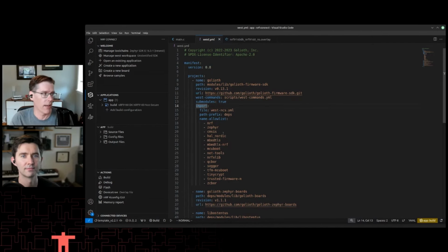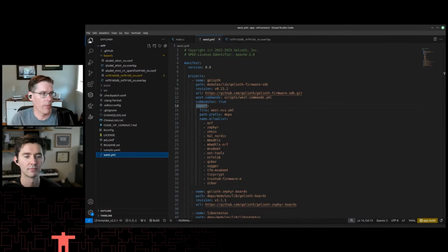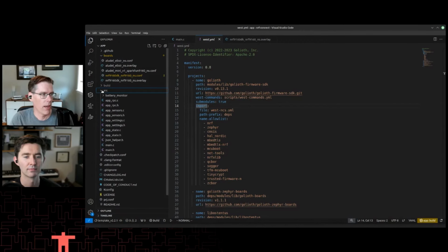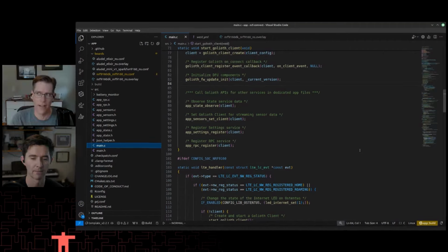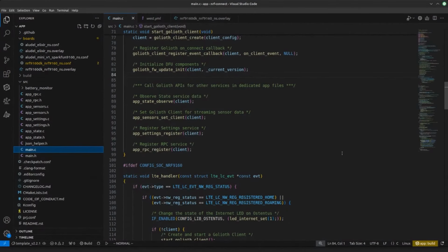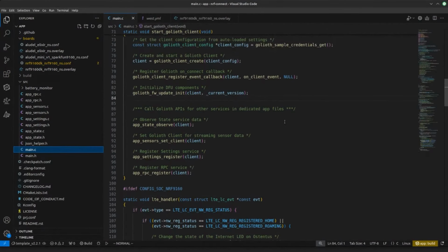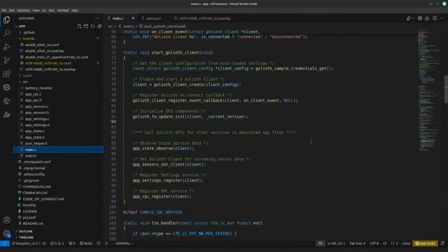I think today we're just going to jump in to a little bit about the way that Golioth works. So Golioth is a module that gets built on top of NCS, or nRF Connect SDK, for Zephyr. And the magic of that is you turn on some Kconfig and you put a header include at the top of your file, and then you're able to start calling API calls.